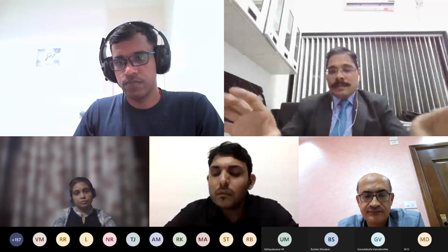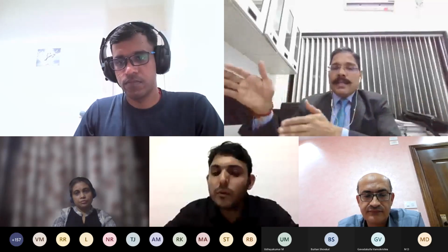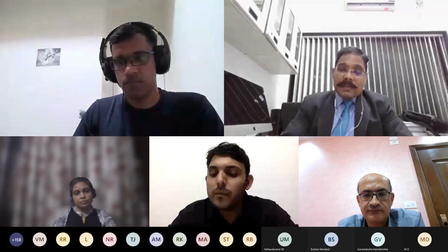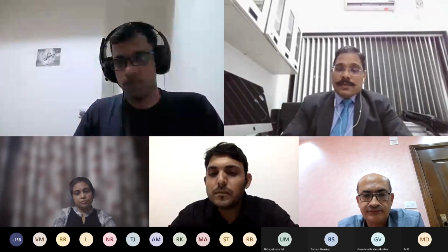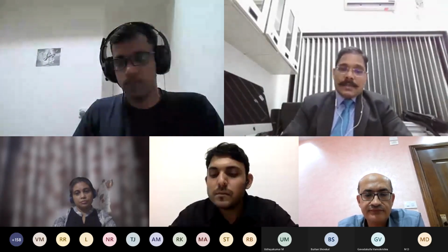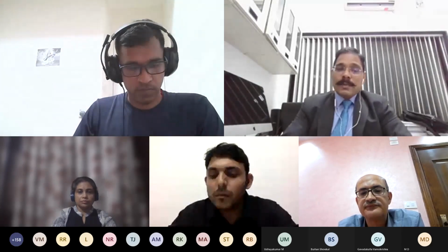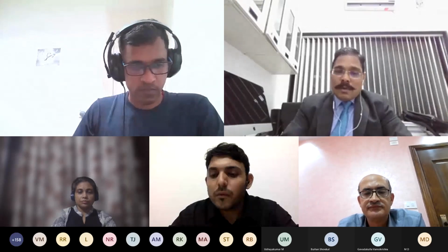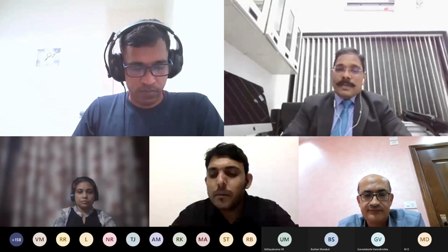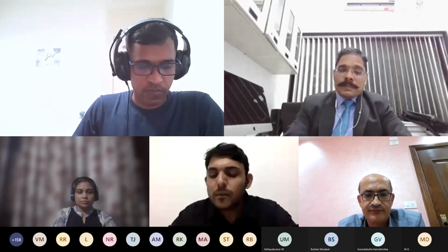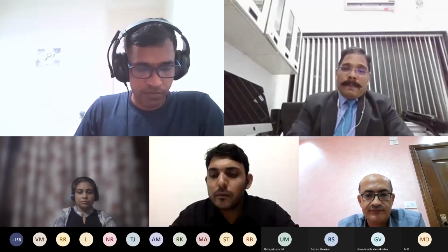They have the stabilized layer, and the stabilized layer has different kinds of ranges given for UCS. But if you go for very high UCS values, then there are certain challenges that you have to handle. Reflective cracks may come up, and it may not behave as expected. Those things we have to take into consideration. Yeah. Thank you, sir.